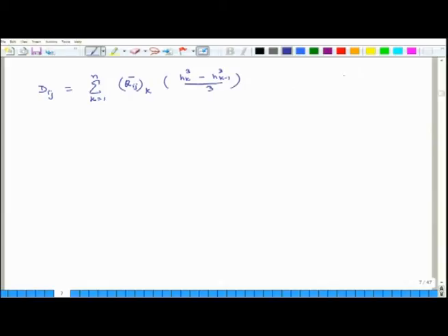Once again we draw the laminate cross section. This is the mid plane, this is the end of the first layer. So, this is the 45-degree layer, this is the 0-degree layer. Here z is equal to minus 4, here z is equal to 4, here z is equal to minus 1.